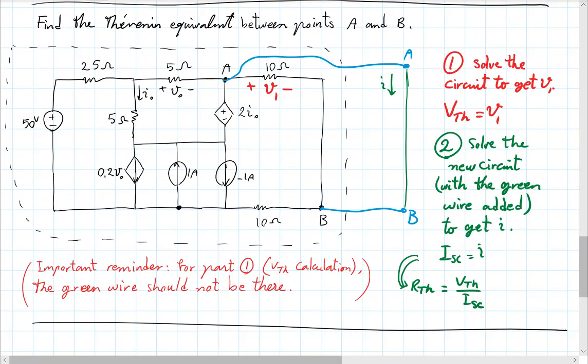Yeah. So the question was this. Now imagine the other problem where I said, let's see what the Thevenin equivalent is between points A and C. So if I brought out a wire like this, I said the Thevenin equivalent between points A and C rather than A and B. So scrap B, between A and C. And so you have, again, the open circuit voltage that you have to calculate, as we discussed. And then you also have to calculate the short circuit current, right? And the question was, what happens to this? Yeah, how to deal with it?